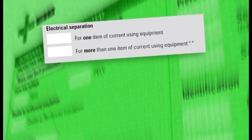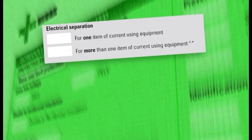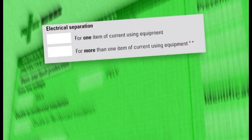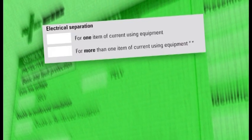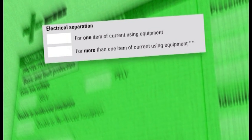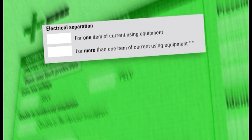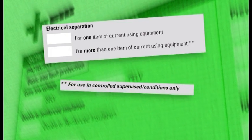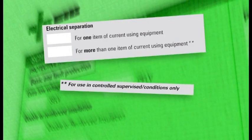On the schedule there are two boxes under electrical separation. One for where one item of current using equipment is connected, which is the most common, and the other for when more than one item of current using equipment is connected to the same source of electrical separation. This second option is only suitable for use in installations controlled or supervised by a skilled or instructed person, and this would need to be checked.